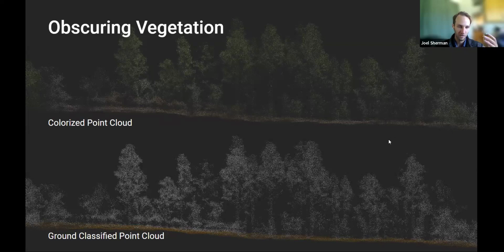And then what we're able to do, like I mentioned in the prior slide, is classify that. We're able to post-process the data and say, okay, of all these points, which of these actually represent the earthen surfaces, which is what we care about, and which of them do not, which of them are a tree canopy or some other obscuring object. And then we're able to classify them and filter them out and literally strip off all of the points that aren't relevant for the earthen profile. You'll see that it looks a little fuzzy here, and that's because it is a 6-foot wide swath. It's not just a nice clean 0.2 foot width. It's much deeper than that. So it's going to be a bit fuzzier because it's also accounting for changes in elevation and the depth of the image too, right? Because there is a representation in depth here.